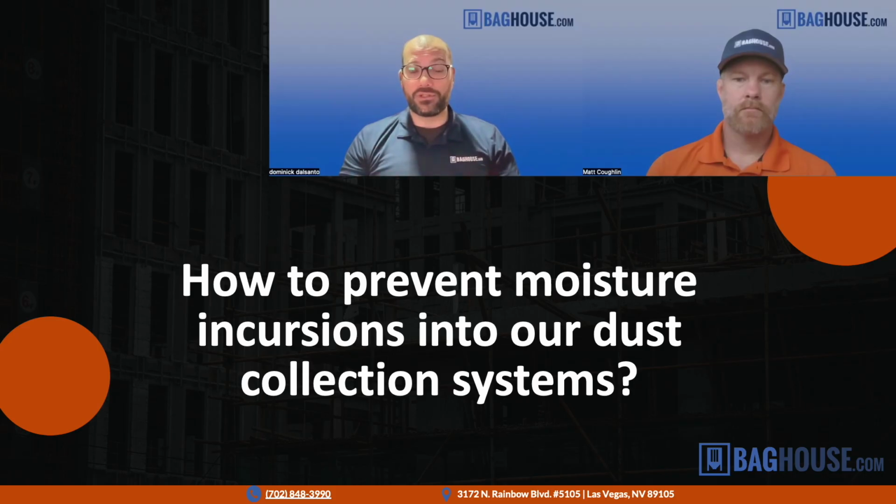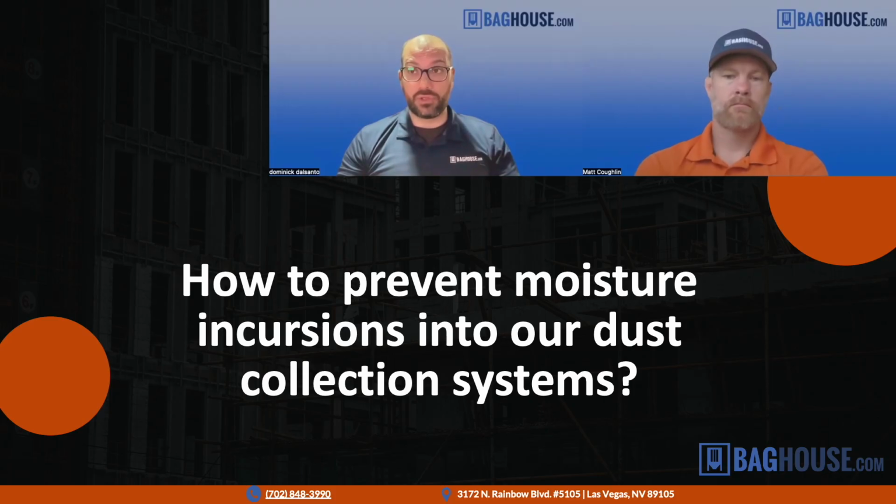If you do have moisture that gets sucked up, say, we have a lot of gypsum and things like that. You have a lot of kettles and batch cooking and things like that, where you have moisture that comes out, you get steam. You can handle steam and moisture in your dust collection system, but everything must stay warm. You cannot have any condensation. And that's not so much the moisture, it's avoiding condensation. So if you have that, it's actually your friend to keep everything very hot.